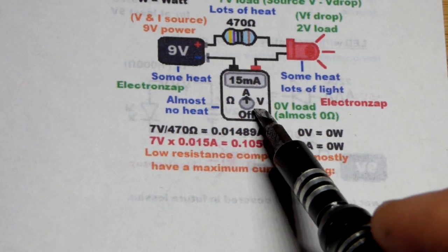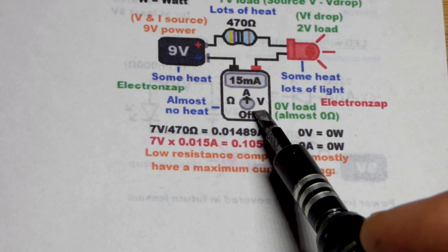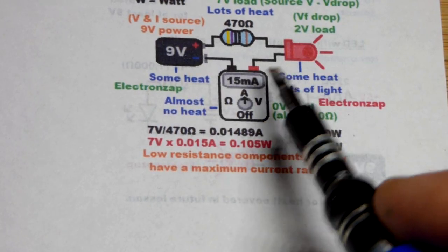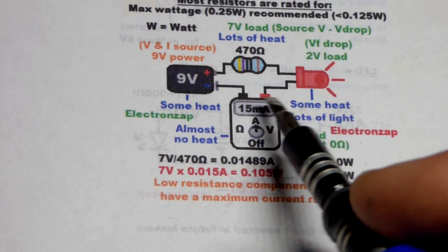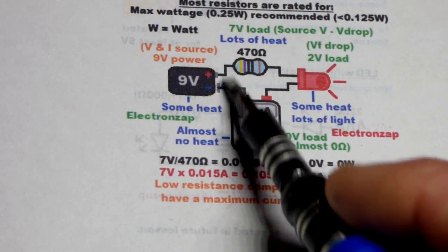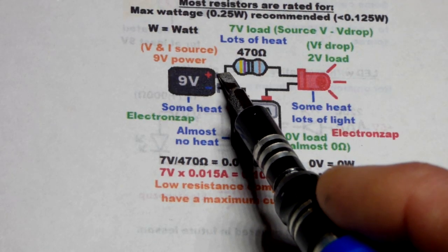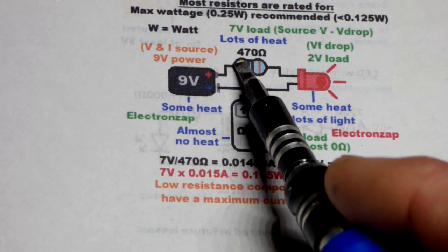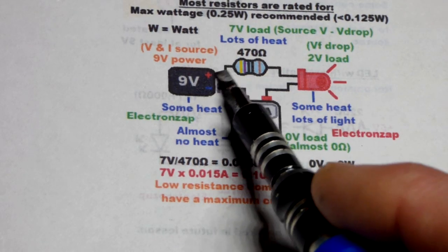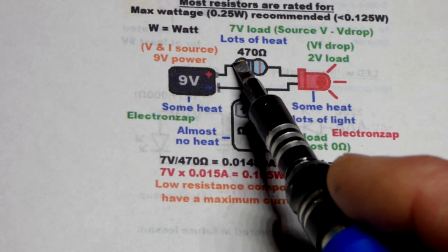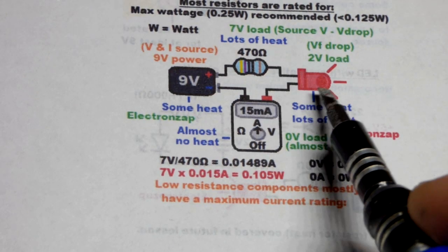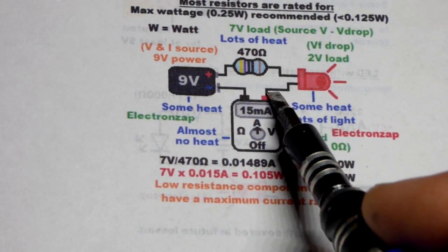Hopefully that makes sense. Now, when it comes to the meter, when you are measuring current, you notice this is part of the circuit. Each one of these parts has two points where it's connected to the circuit, an input and an output almost. So that would be a wire going to the positive supply, and then you might have other connectors, but hopefully they've got no resistance. Basically it's a direct connection. And then the other side, resistor, direct connection to the anode of the LED, cathode, direct connection.